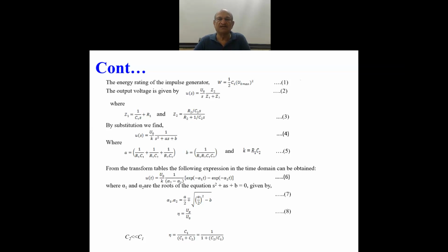Even the design of the impulse generator has improved a lot. As we increase the transmission voltages, the switching surges rise proportional to the rated voltage. So we need to test our equipment in the network with high switching voltages, and high lightning impulse voltages are produced up to a maximum of 7200 kV. The switching impulse voltage is slower, up to 5000 kV, and needs the ratings of the components of the impulse generator to be larger.